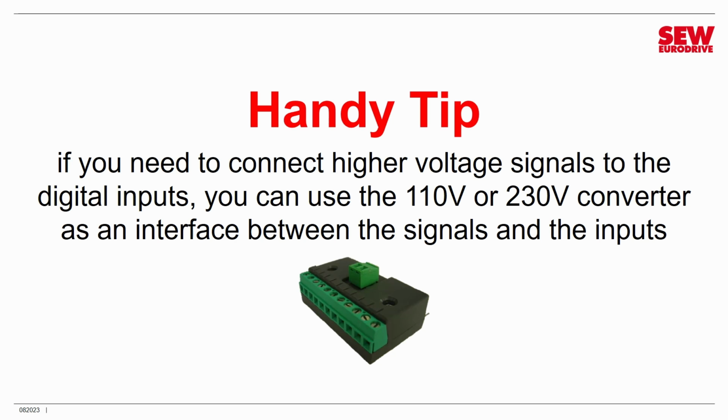Let me give you a handy tip. If you need to connect higher voltage signals to the digital inputs, let me remind you there is a device called the 110-volt or 230-volt converter card. You can use this as an interface between these higher voltage signals and the low voltage digital inputs. So if you add this, it scales the voltages appropriately and allows you to safely control the VFD using higher voltage digital signals. So file that away in your toolbox. It might be handy.